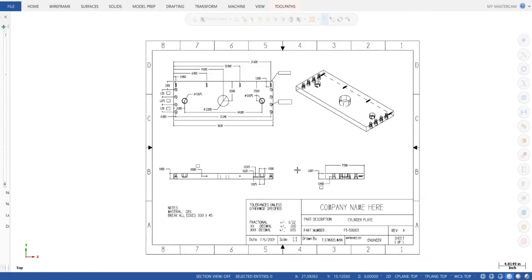So those are some of the basic things I look for. And as a CNC programmer, you'll probably look at a lot of prints, especially when you're quoting them. You just kind of have to scan the prints for that basic information we just went over and just in your head process how many different setups it would take. In this case, it would take 3 setups, top side, bottom side, and the holes on the side. So that gives you an idea of how much time you would have to spend programming, setup, and then actually machining those features.